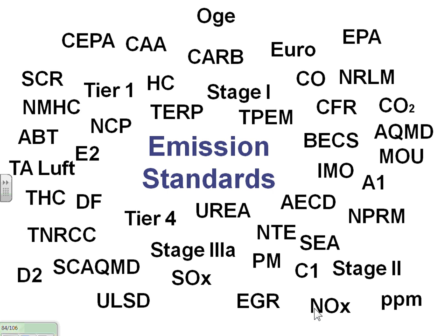It's not the SCR you're thinking of. It's selective catalytic reduction. What that does is we introduce urea into the exhaust stream, and it becomes ammonia. It wipes out a lot of the NOx, and we can reduce it by up to 90%, which is what the EPA wants.